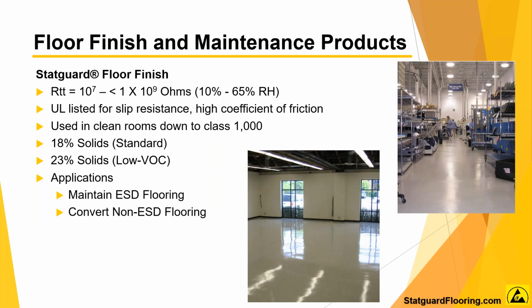We offer our Statguard Dissipative Floor Finish, which is a dissipative cross-link polymer finish, and our Statguard low VOC dissipative floor finish system. Our ESD floor finishes will convert a non-ESD flooring to a static dissipative flooring. Both floor finishes have a resistance of less than 1 × 10⁹ ohms. They are UL listed for slip resistance at 10 to 65% RH levels.